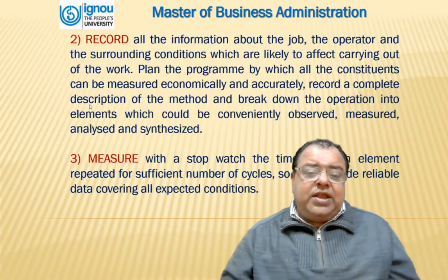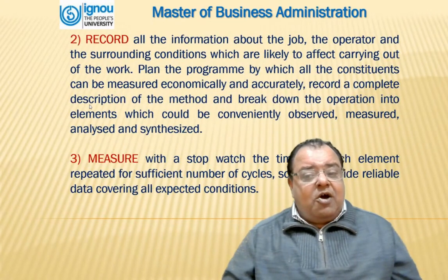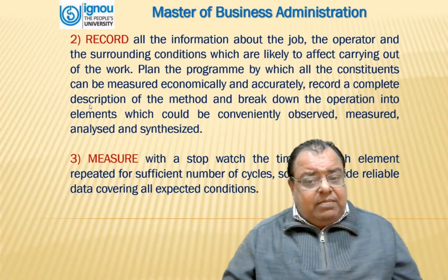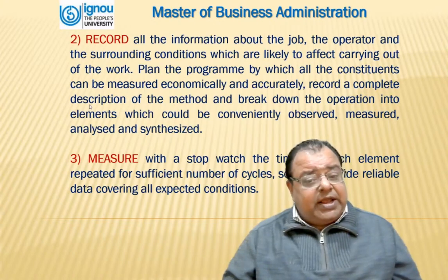Second, record all the information about the job, the operator, and the surrounding conditions which are likely to affect carrying out of the work. Plan the program by which all the constituents can be measured economically and accurately.